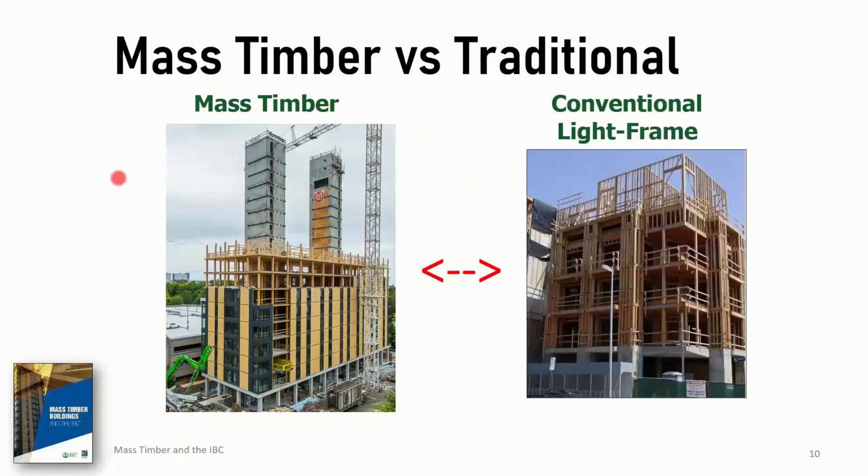And if you're perhaps skeptical about the increased heights and so forth, let me just start by saying everything you see here is not permitted over here. You're seeing studs, you're seeing joists, you're seeing repetitive member assemblies. Light frame wood assemblies are not permitted as floors, walls, or roofs in this construction type.